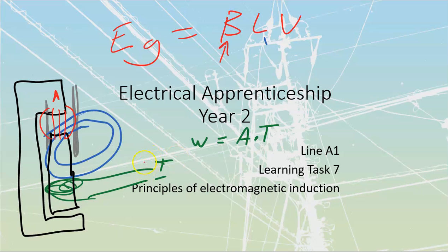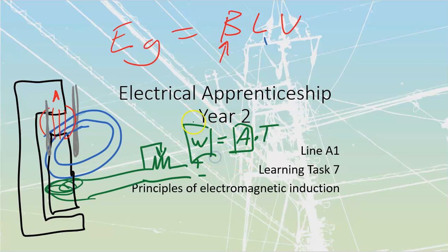We usually control all of this by just putting something in line with this. And usually it's going to be something like a rheostat, which is a variable type of resistance, so that I can adjust the amount of current that is going to be traveling through this coil, which would then adjust my amount of amps over here, which would then adjust my amount of Webers, which would then adjust my amount of flux, my flux density, my Teslas over here, which would adjust my amount of voltage.